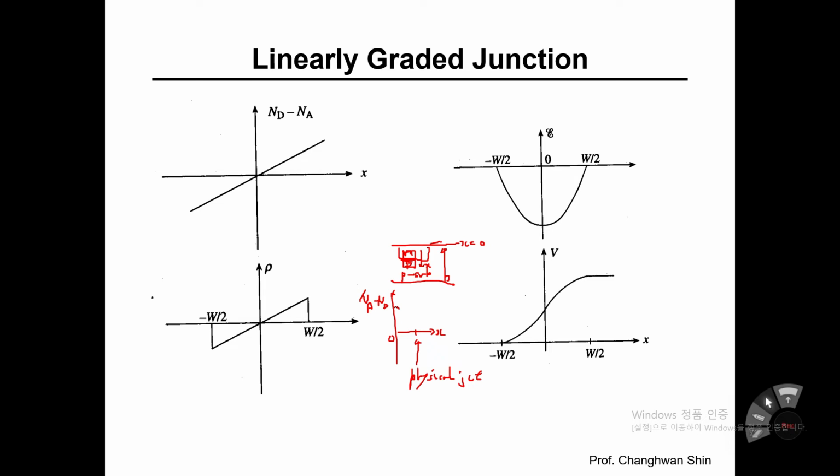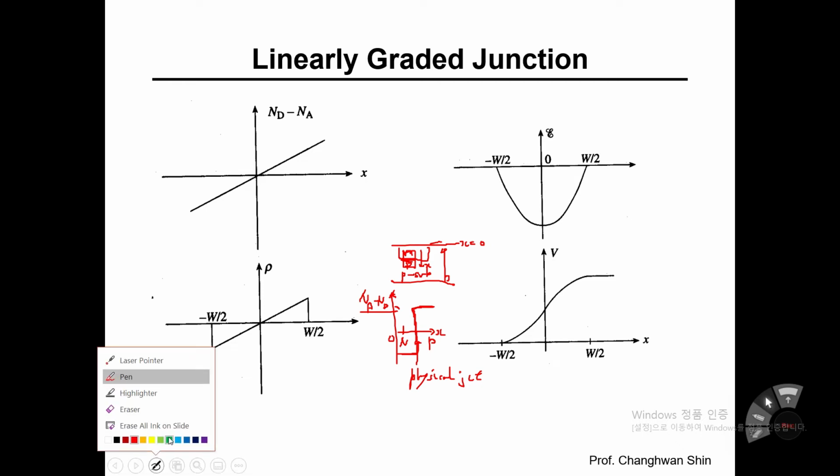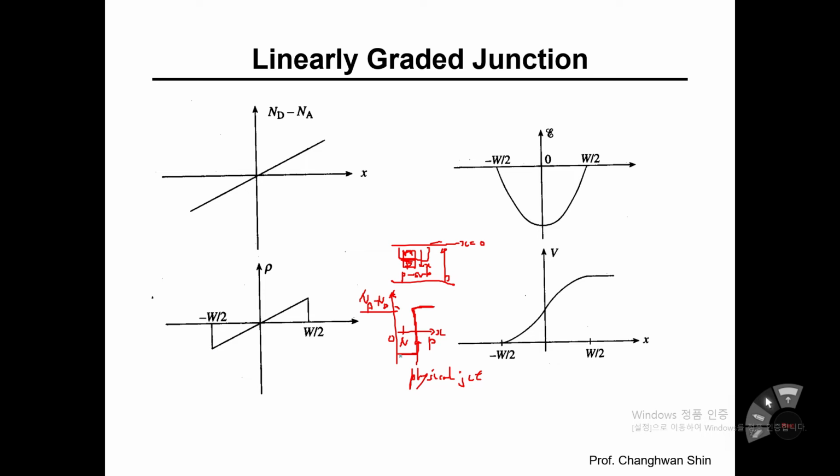The top side of the silicon substrate is N-type and the bottom side is P-type. Therefore, the y-axis is N_A minus N_D, and this doping profile is ideal for the PN junction. But the problem is the process engineer could not fabricate this red-colored step doping profile. So for a while, this was the best one in terms of doping profile in a PN junction diode.